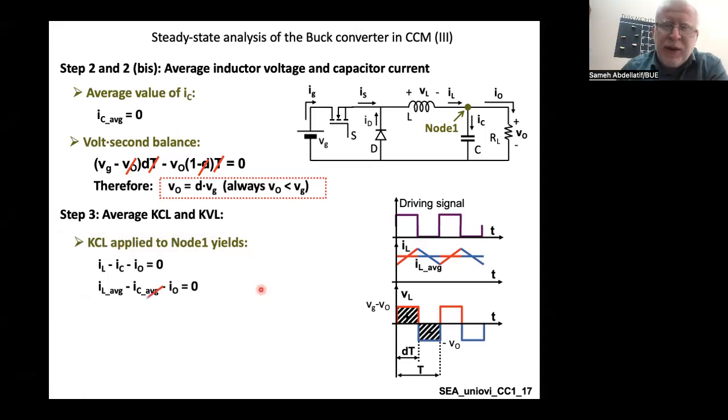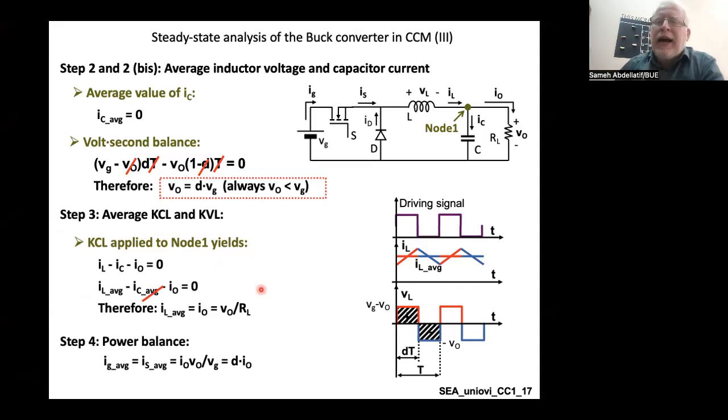Okay, so in the previous part of this chapter, my dear students, we have recognized together what's called the buck converter. And we have studied the main architecture or circuit schematic for a buck conversion. A buck conversion means simply to buck, or to reduce, or to step down your output voltage with respect to the input voltage. And we reached a mathematical formula that governs this relation, saying that the output voltage is equal to D times the input voltage, where D here represents the duty cycle, or simply the rising time of your driving signal with respect to the complete period.